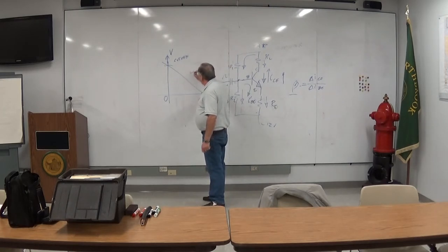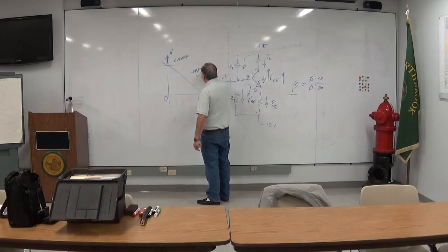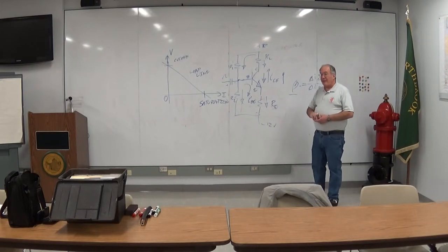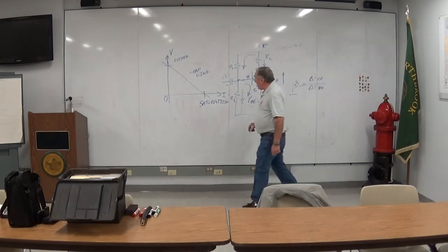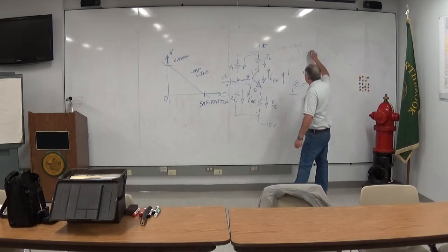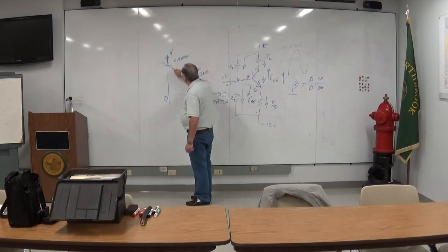And that's what this thing is called, a load line. That is based on the load resistance here. In other conditions, it is going to be the slope of that line. And what's going to happen is, if I put a signal in here and I get an amplified signal out here, what's really happening is I'm sort of in the middle and I just go this way and I go this way, up and down the load line.